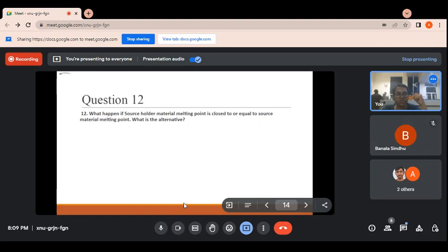Okay. So for silicon dioxide etching, we use the buffered hydrofluoric acid. When you go for silicon dioxide etching using the buffered hydrofluoric acid, it etches in all directions. So in all directions it is etching the silicon dioxide. Whenever the chemical etches in all directions, it is called isotropic etching.